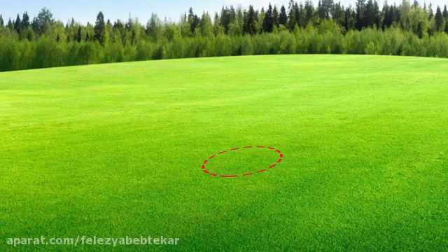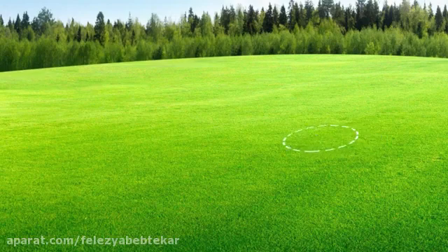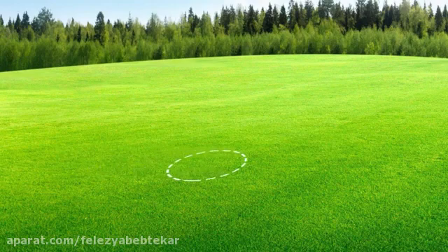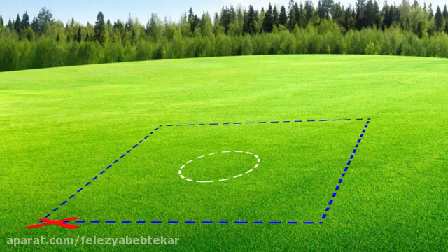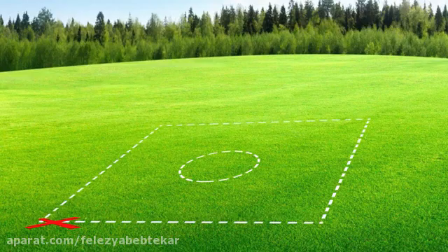The first step of the scan is to select the scan location where we think the anomaly is located. The condition of an ideal scan requires that the scan site be flat and with very little unevenness. Select the dimensions of the scan area so large that the entire target you are looking for is completely in your scan area. The size of an ideal scan is 3 to 4 times the size of an anomaly.